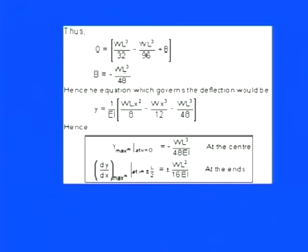But now our main intention is to find the maximum deflection, and always when we put the point load at the center, we have the maximum deflection. So by putting x equals L by 2, we have the maximum deflection value. Here, we are simply going up to L by 2. So what we have is minus WL cube by 48 EI, because this x is gone, this x is gone, so we have only this value. This is the maximum deflection.